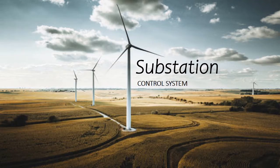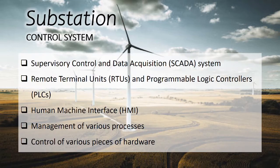Next, we will consider the substation control system. The substation control system is implemented as a SCADA system, which is a hardware and software network that automatically monitors substation processes, enabling efficiency and well-informed decision-making. The central server of the system is hosted on a computer that communicates with RTUs and PLCs, which translate in-system and sensor output data into digital data that is sent to the server to be processed. Operators interface with the system via an HMI.